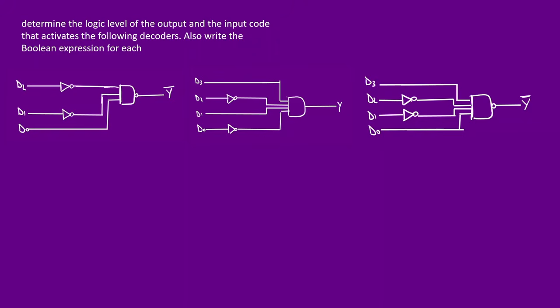So they are much more simplified forms of decoders where what will usually be complex, we're going to take a snapshot of it and have only one. All right. Recall that decoders are able to transform n input lines to 2 raised to n output lines. Okay. So if I have 2 inputs on my decoder, I'm going to be able to get a maximum of 4 output lines. All right. So seeing that we have 4 inputs here, this is a single gate decoder because it takes just one scenario out of all of that.